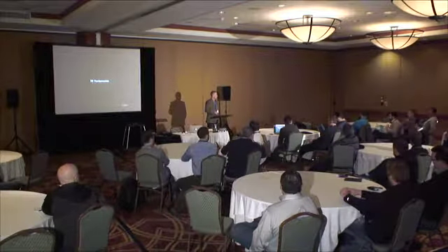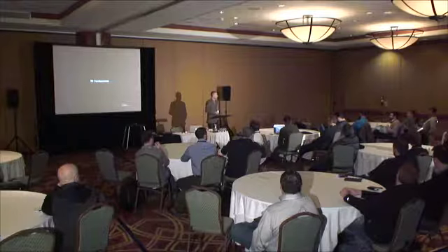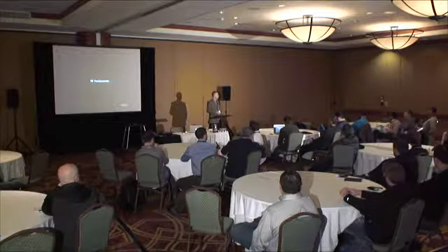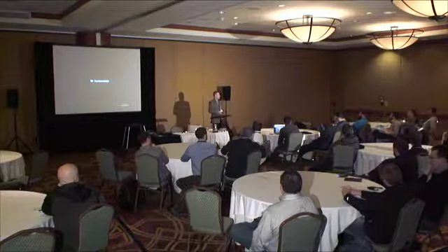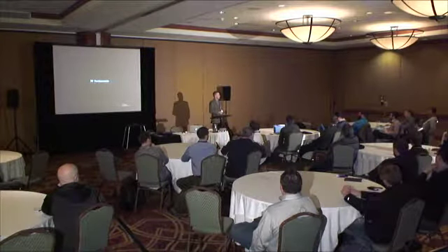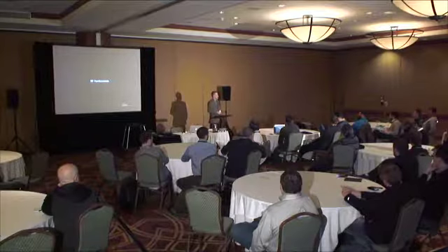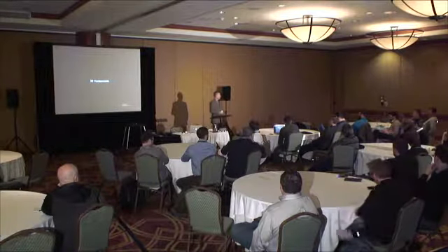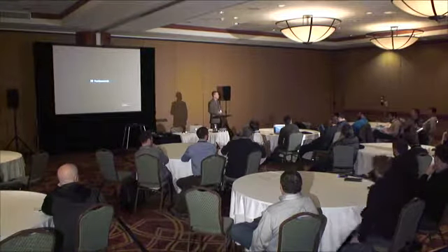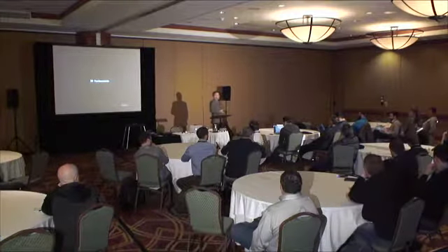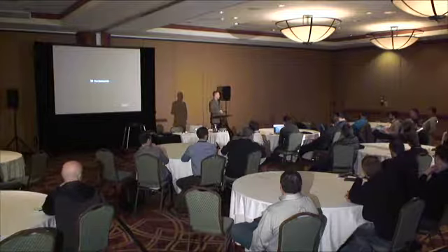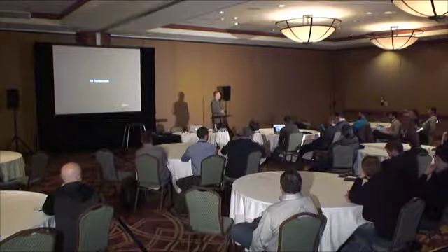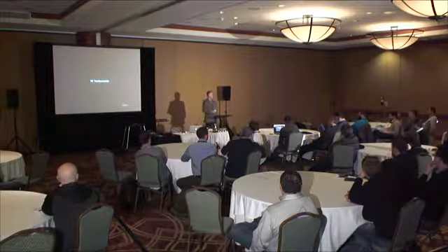My thoughts are to follow what Keith does, which is what I call an enhanced predictive, where you're on-site, getting all of those things you can't get off-site. But where it falls apart for me is taking wall attenuation measurements on site and putting them into Air Magnet, and you've got real values, and you can see the ceiling, you can see everything. But in a warehouse, you can't really take a wall attenuation value because it's not a wall, and are you getting real values, and again, the stock on the shelf. So what are your thoughts on using predictive?